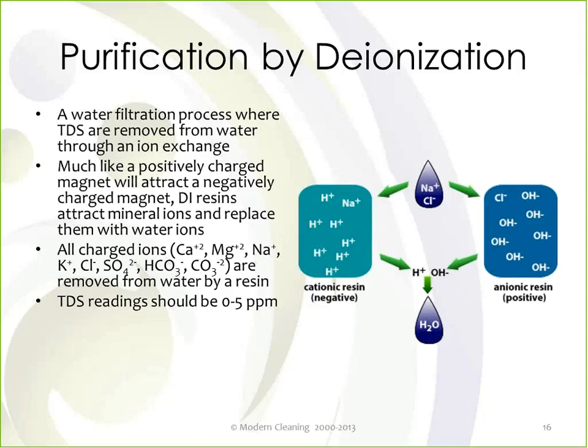It's not uncommon to see readings of 0 to 5 parts per million. That's really what you want to see. Then you know it's pure. And it's our experience when you're measuring this, and we'll be talking a bit more about measuring total dissolved solids, you typically get a reading of 0 if everything's calibrated correctly and the filter is good. But you can go up to 5. When you start seeing it creeping up, you know your filter probably is pooping out or getting full.